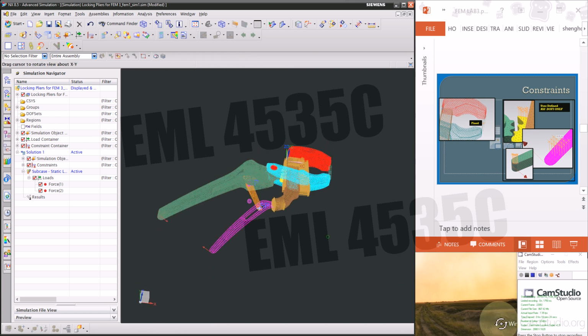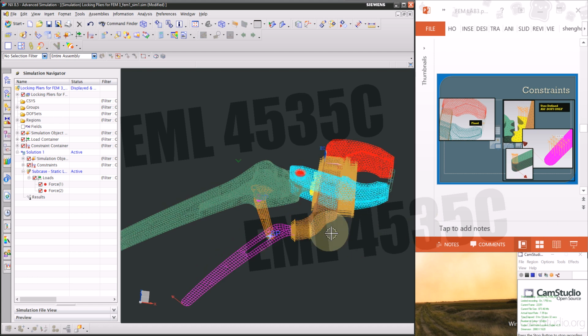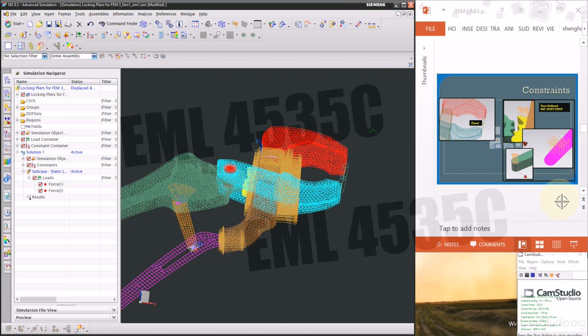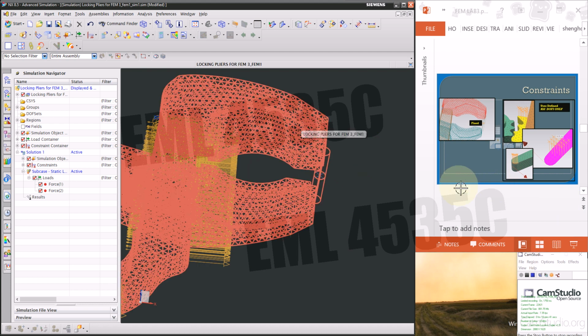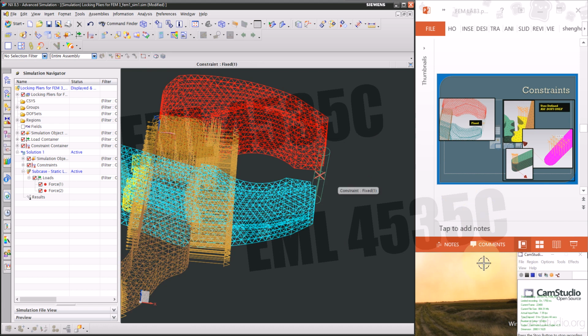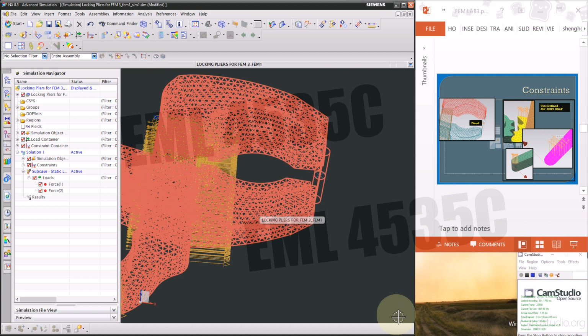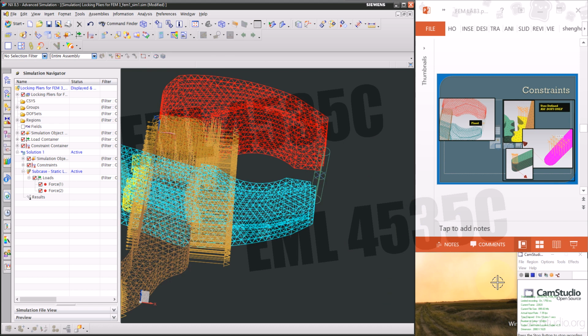This is not in real life. In real life, this is enough to squeeze your pliers. But in a simulation, there's a mechanism here which he will talk about in the class. The tetras, these things, don't have degrees of freedom 4, 5, 6. So you do a fully fixed constraint here. Once the constraint is transferred into 3D tetra, they don't have rotational degrees of freedom. So that means those 3D tetra are free to rotate on 4, 5, 6, even though you've killed all 6 degrees of freedom in the C-bar.